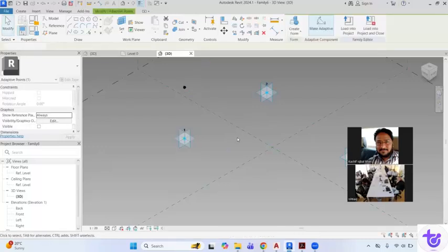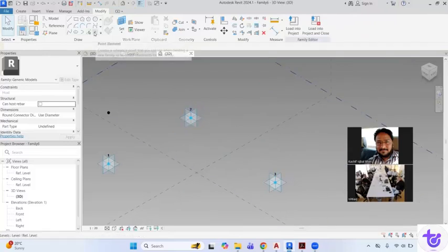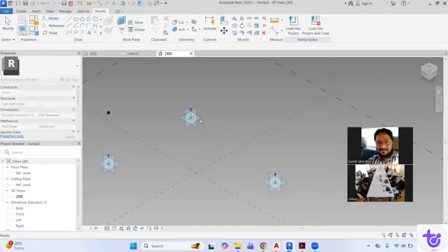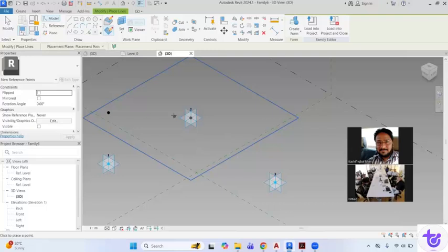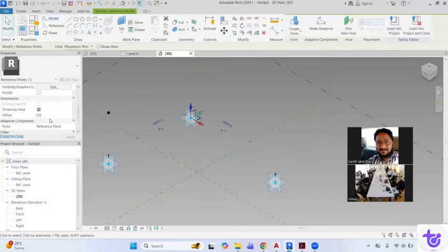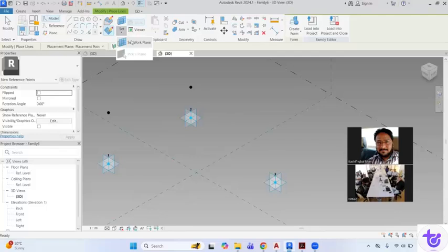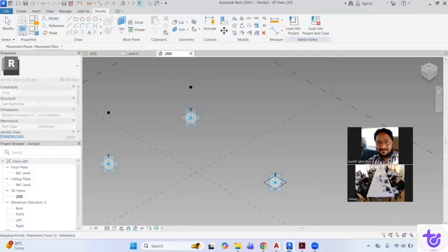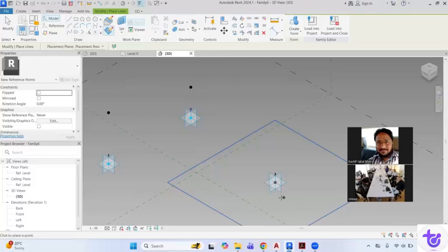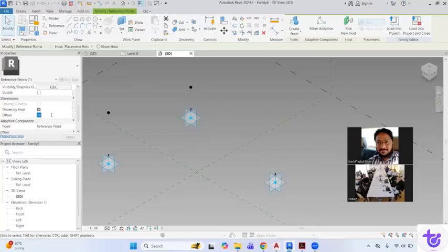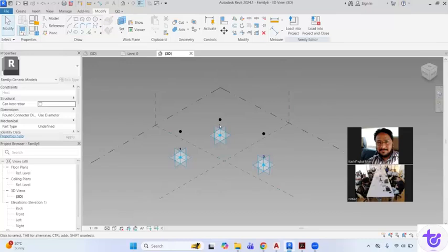And then again, when I take the reference, drawing on the reference plane, select the work plane, this point, and then put the point here. Now give some value, millimeters. Repeat the process here. Give some value. Done. Step 2 is done.